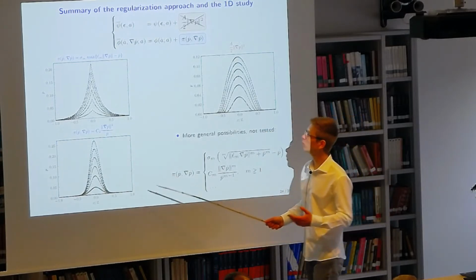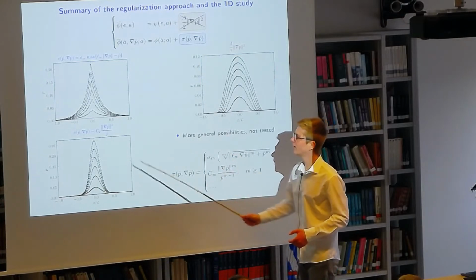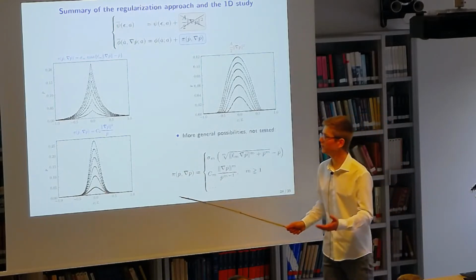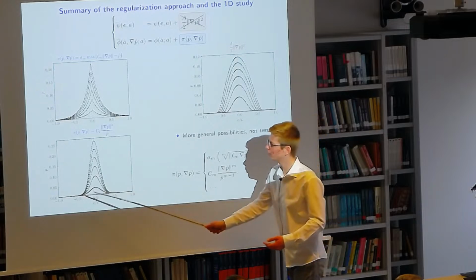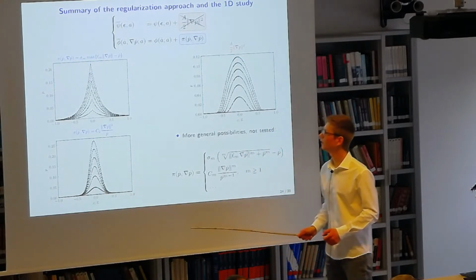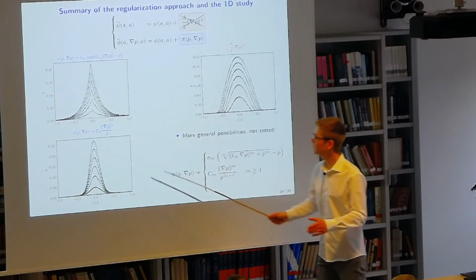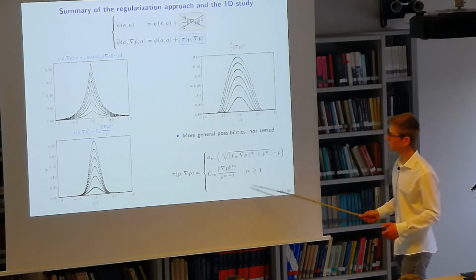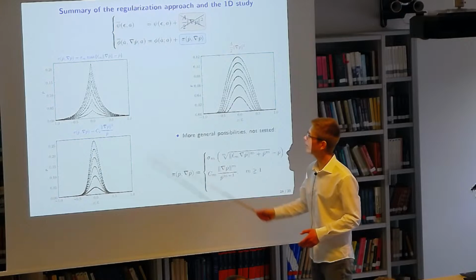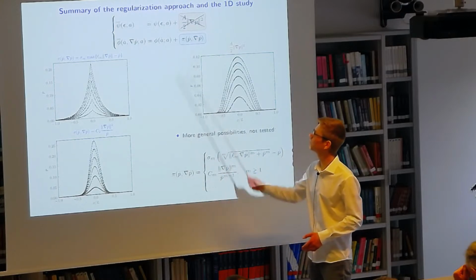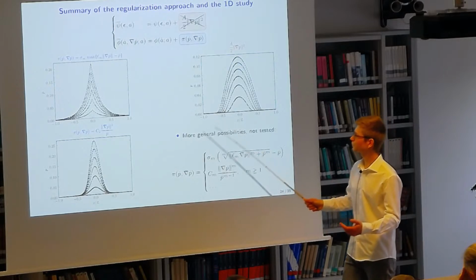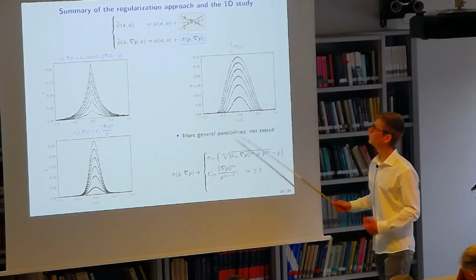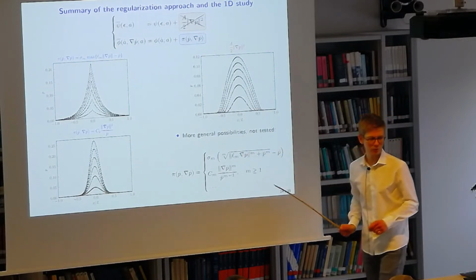In fact, when we also try other expressions for defining this function pi, such as this one, which is going to be named a quadratic-on-linear potential, we also observe quite similar properties of stationarity with the evolution of the plastic band along the loading. More generally, these two examples can be embodied in more general ones which are defined by semi-norms, for instance with an index m larger than 1. And in comparison, our approach, which relies on the dissipation potential, allows us to have plastic bands which can be much more confined in comparison with the more usual regularization by the quadratic term in the free energy.